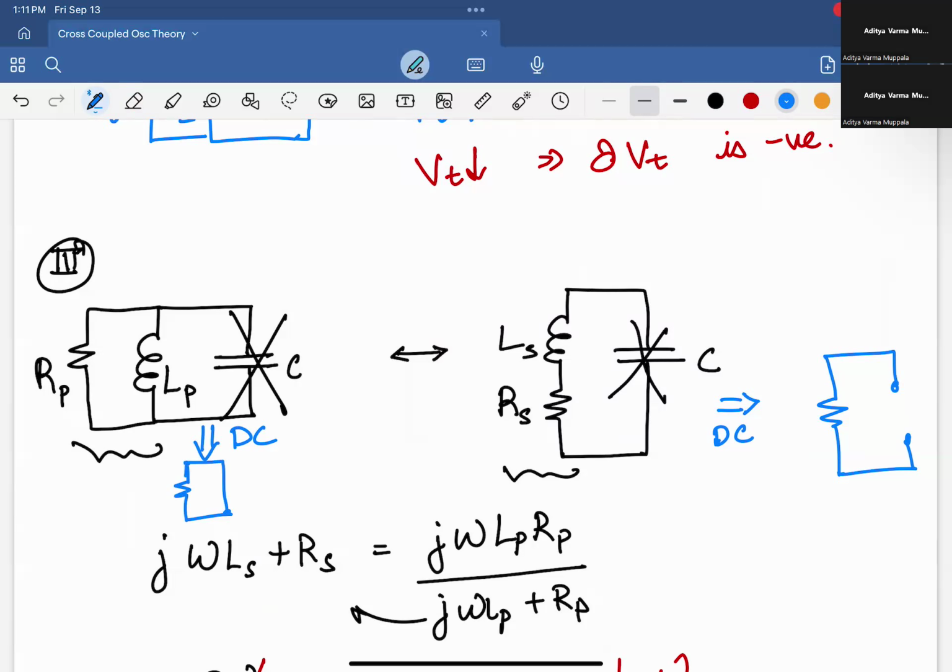Whereas at infinity, at infinite frequency, very high frequency, at omega equal to infinity, you have the opposite case, right? So the capacitor is shorted and the inductor is open. So that thing is short like that. And then in this case, it's the same actually. Like that, capacitor is short, inductor is open. And this one has a model like this, right?